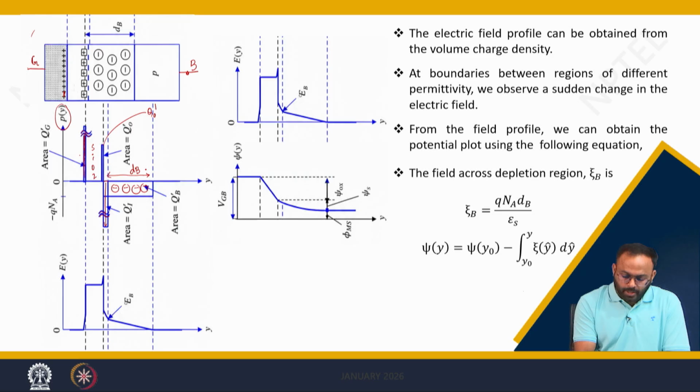If you see this charge density curve along the device dimension, you will get this figure, and it says that all the possible charge is actually in balance. Considering the depletion approximation and charge sheet approximation, we can simply say that this thickness can be ignored with respect to dB. Now the total body charge per unit area can be given as minus Q into Na into dB.